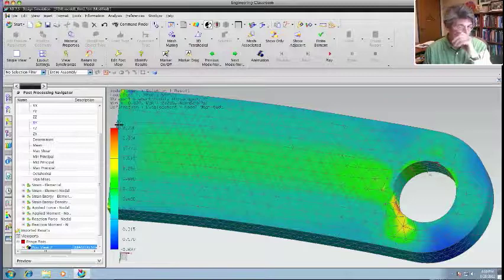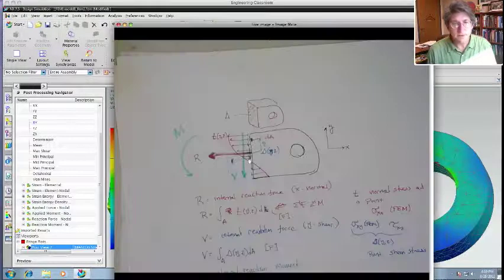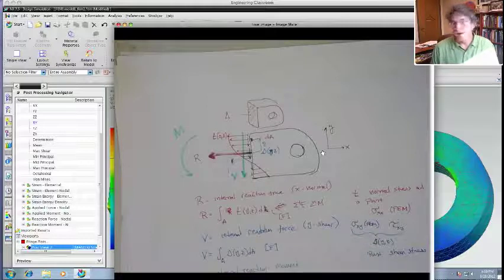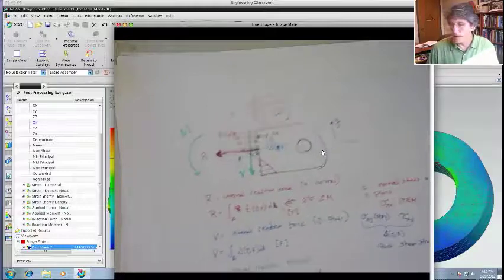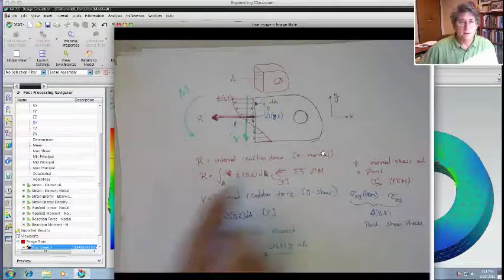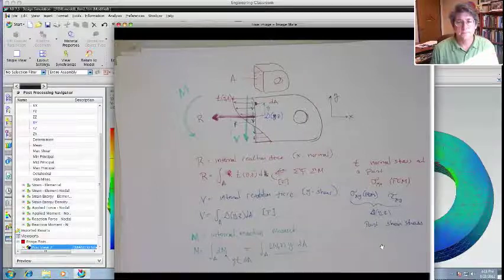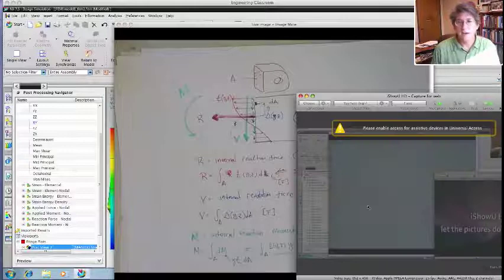Okay. Actually, when we go to bending, you'll see that there's a refinement we do on here to capture the bending stresses more accurately. But this is just a simple example to show you this visualization in class. Okay. So it's fine from now on to remember these stresses as force per area, but really don't lose sight of the fact that they're actually pointwise values, and they vary across the cross-section. Okay? All right. I hope that helped.